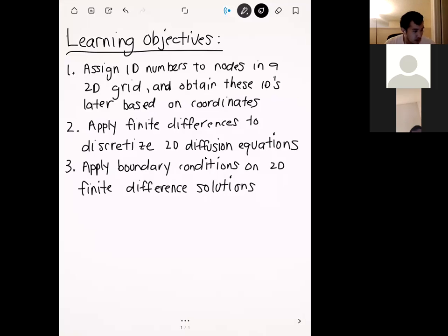Okay. Last time we met a week ago, we had just finished our lecture notes on 1D diffusion. Basically, we applied the finite difference method to a 1D diffusion equation, and we saw how we could simulate that in MATLAB. So this week we're going to take it a step up and simulate the 2D diffusion equation. With 2D, we'll have two different spatial dimensions, both x and y.